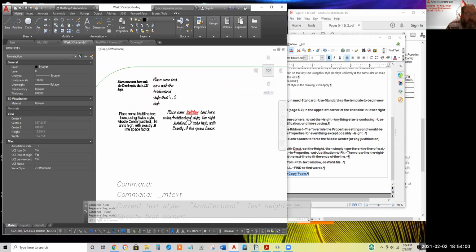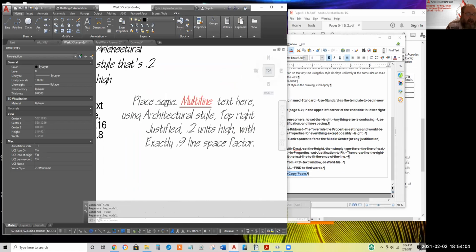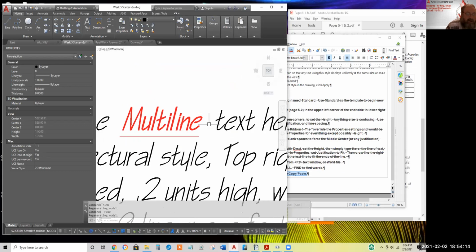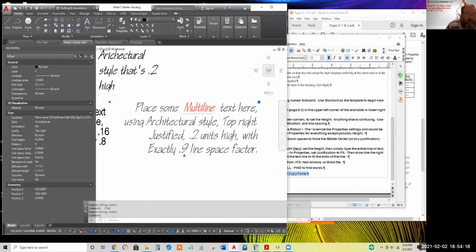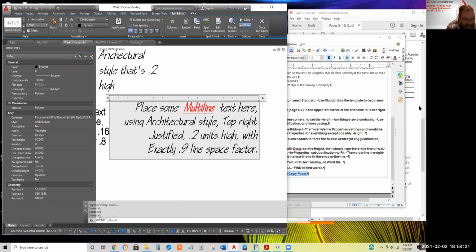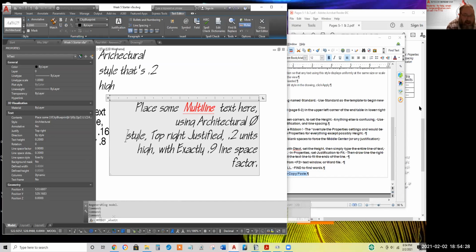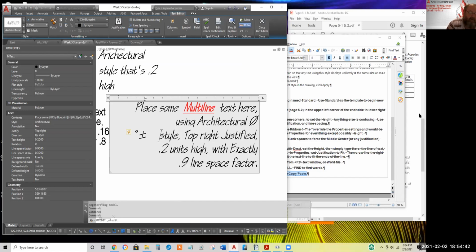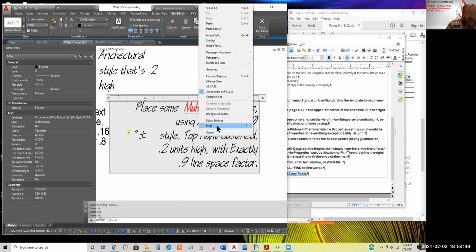Okay, there's a few symbols that have lasted throughout AutoCAD's history. For example, the circle slash for diameter, a tiny little circle for degree, plus or minus for tolerancing. Check it out. I'll simply type, and I guess you eventually write these down: %C is for diameter. %D gets you that little bubble. And %P gives you the plus or minus symbol. Other symbols, maybe a few others I'm not thinking of, but for the other ones just right click in the middle of the text, go to symbols.